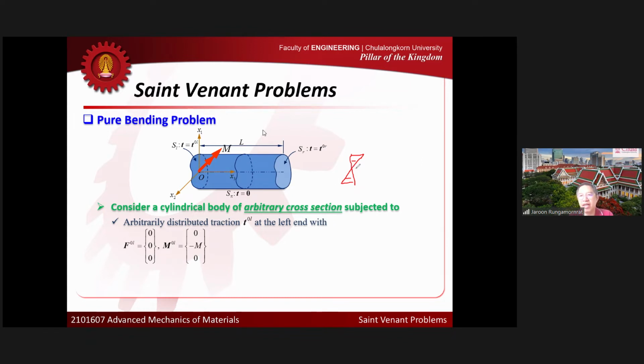When you learn how to calculate stress in a beam at the cross section in beam theory, you know the distribution of the stress across the section like this. If we look at the distribution like that and compute the net force, you will get zero. And when you compute the net moment, you are going to get the bending moment at the cross section. This is one example that can generate the net force and moment like this, but it's not the only one that's possible.